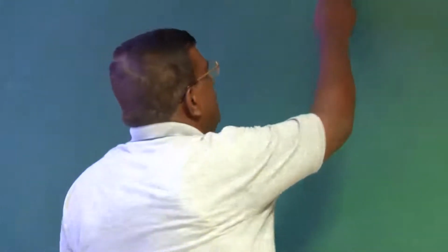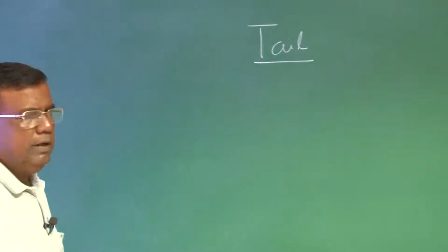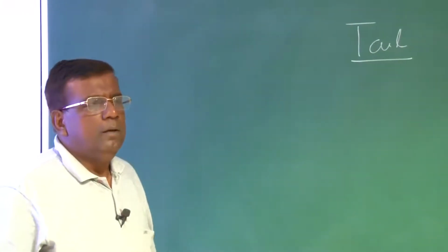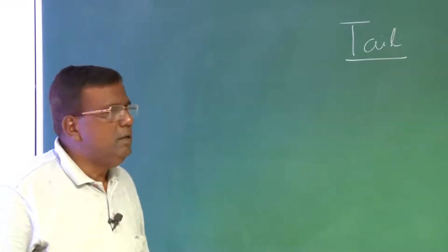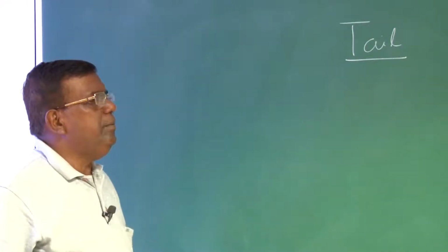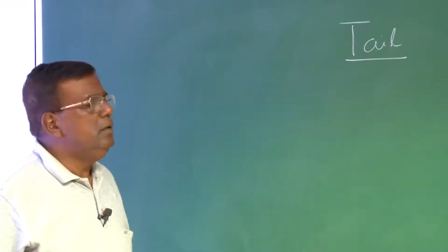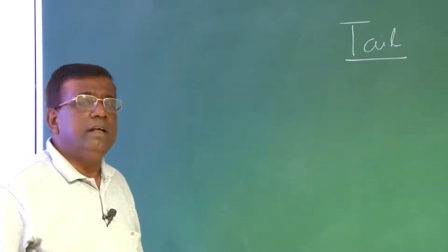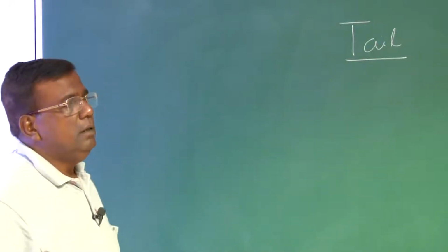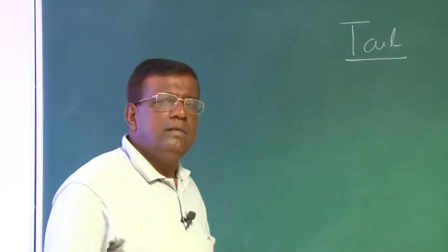In continuation to that, we will also quickly go through most popular tail configurations. To start with, I will not talk about various types of ingenious tails, but I will primarily talk about conventional tail and a T-tail and try to highlight what are the merits and demerits and why it has evolved like that. Any other configurations, we will be talking or discussing as and when required.